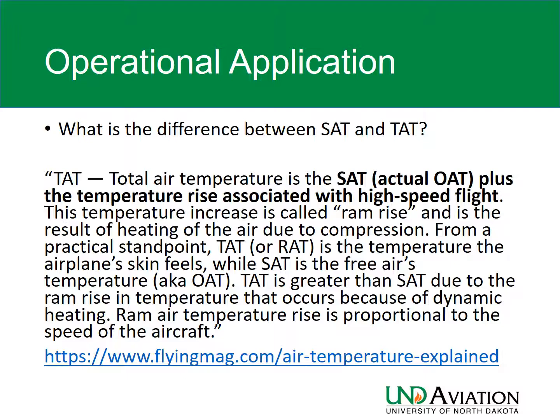And so effectively, you have to understand that SAT and TAT may be used as part of limitations, for example. There may be fuel temperature limitations where TAT may be used, or during use of ice protection, whether it's cowl anti-ice or wing anti-ice. They may be using TAT or SAT in your company manuals to determine whether to use anti-icing protection.